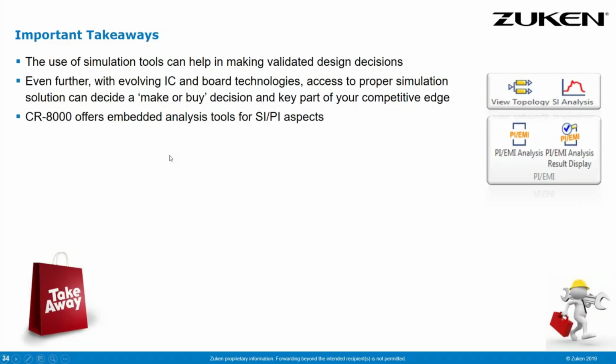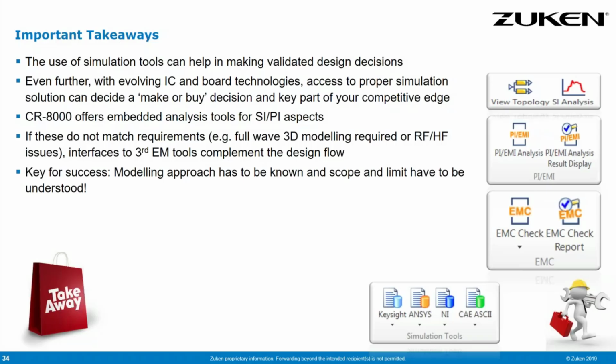CR-8000 offers embedded analysis tools, so you have these analysis tools available within a single or a few mouse clicks. You can generate topologies, you can run transient analysis, you can run frequency domain analysis. In the same manner, you can run a power integrity analysis, you can run EMC checks. If these tools do not fulfill your desire because you have to model any kind of interference to an enclosure, then there are interfaces to third-party full-wave EMC tools, like from Keysight with ADS, like from ANSYS, which is HFSS, or like National Instruments, or CST with Microwave Studio.